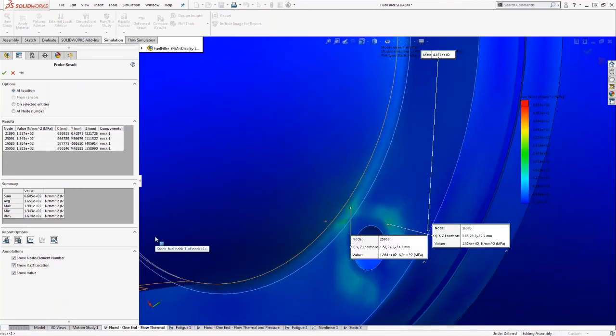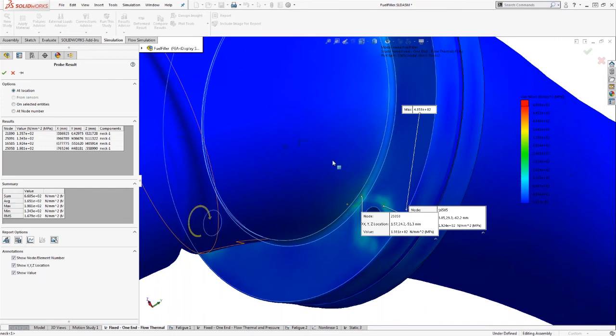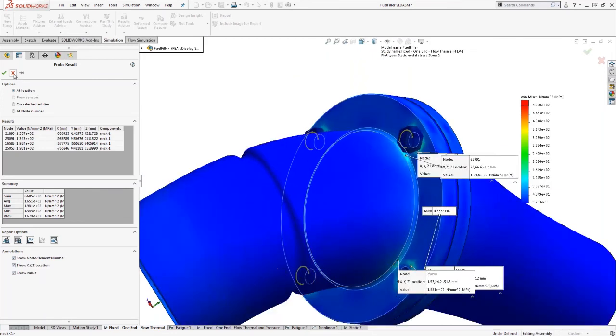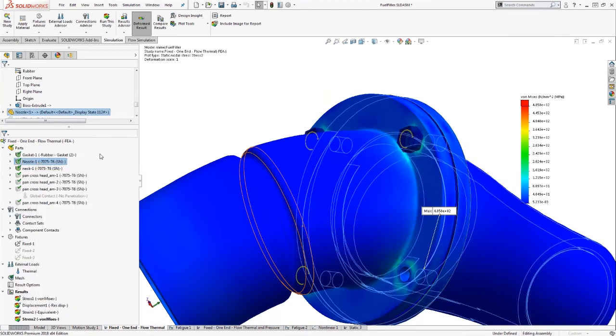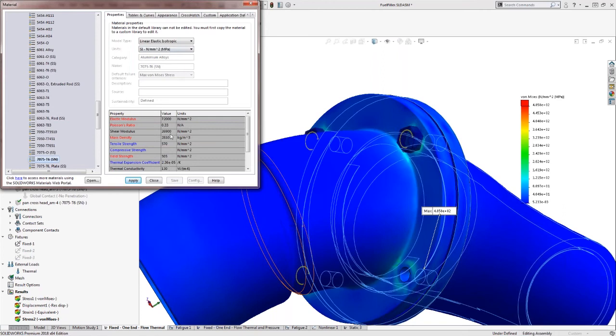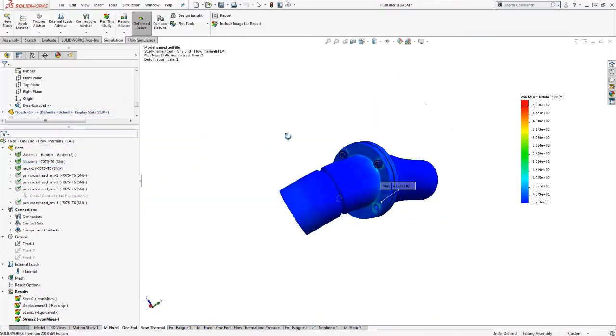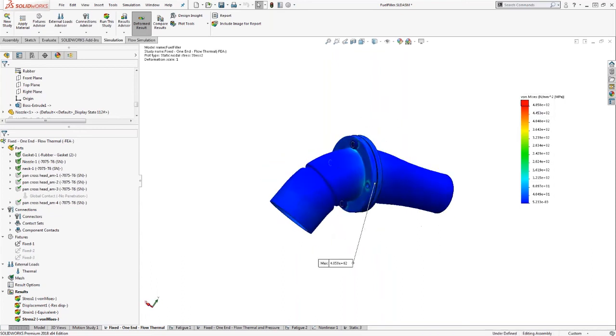And again, we can compare those specific areas to the yield strength of the material, right? And everything here is generally under 200 from what I'm seeing or what I selected. And if I look at 200 MPa, and if I look at the yield strength of the metal itself, you see that the yield strength for this specific metal here is about 505 MPa. So again, the overall model is well under the yield point. This high stress is pretty much an artifact, it's not really real, but we can use that hotspot diagnostics to let us know that it's not real, but everywhere else will be okay based on the setup of the model, right?